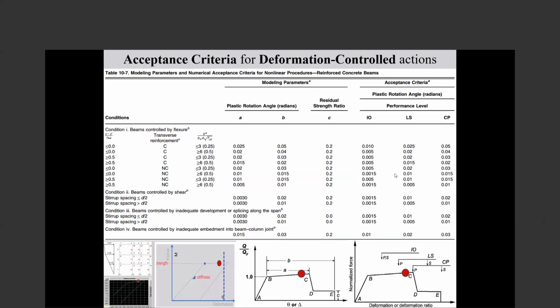So if in an existing building or a new building you find a strange section, for example, one part is steel, one part concrete, one part is, for example, another kind of alloy. You go to the section designer, give the geometry of the section and the different part materials.